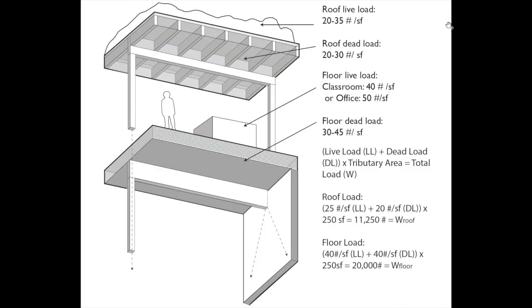With all these, when we're doing our estimate, we'd have to know what the total load is. In this thing, I've made a couple estimates here based on a location and building assembly and overall code guidance. In this, I'm showing that there's a live roof load. In this, there's snow, or in other words, it could be rain. It's showing you a pretty high estimate for what that would be per square foot. The roof dead load is based on the actual assembly materials.